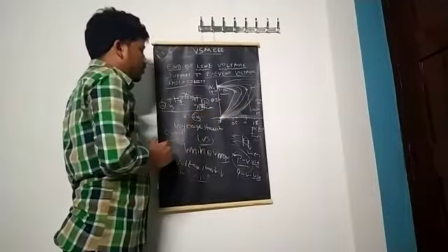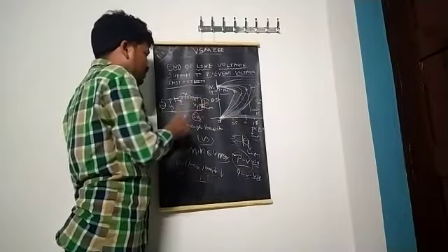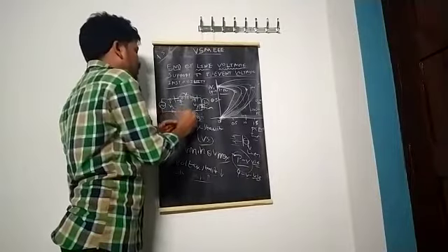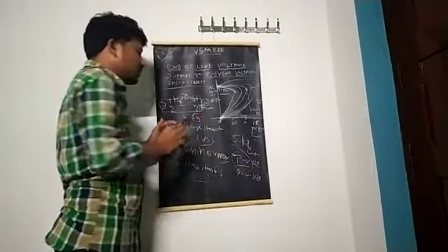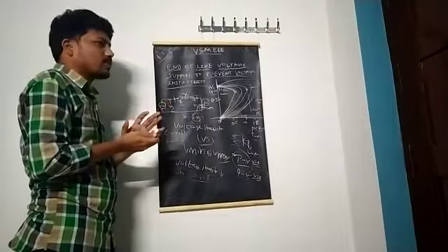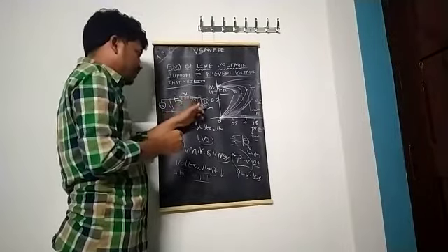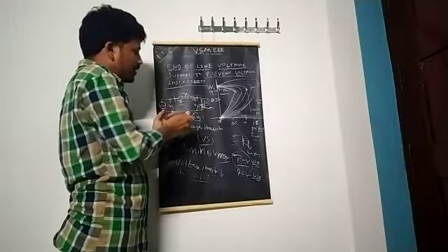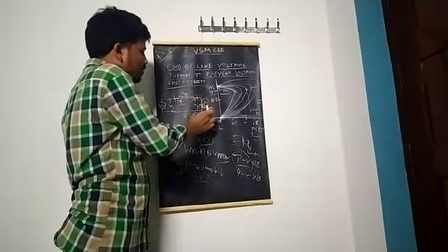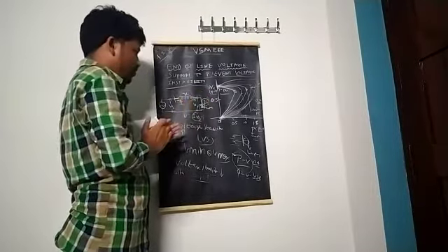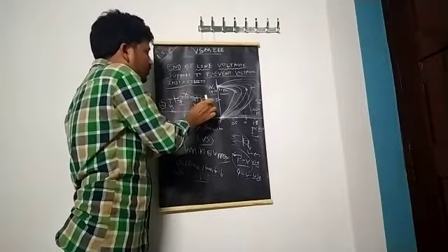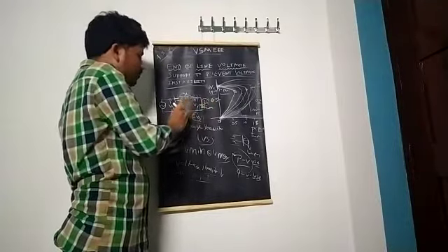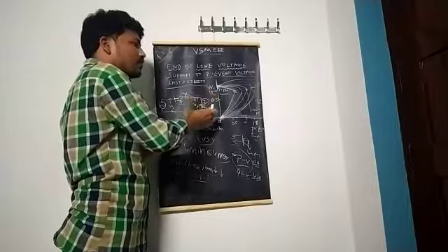if you further increase the load, the impedance will be further reduced. The current drawn will be even more, and the incremental voltage drop will be larger. That means the voltage drop increases fast. Why do we reduce the impedance further? To meet the load demand, which is increasing, we have to supply more current, because the voltage at the bus is always constant. If we supply more current, automatically more power is drawn. To supply more current, obviously we are reducing the impedance.